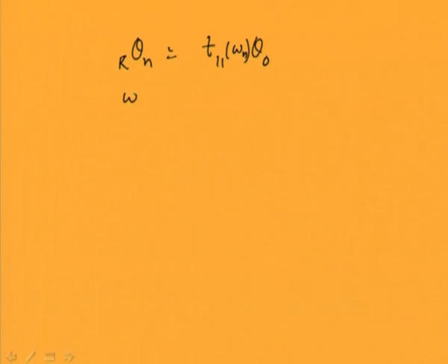So let us say if we want to obtain the mode shape corresponding to the first natural frequency, we need to substitute this here, and this can be taken as a reference, let us say having value 1. Okay, so we can get the displacement at the nth station.